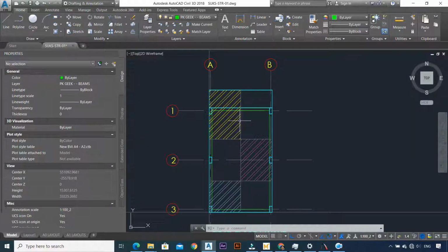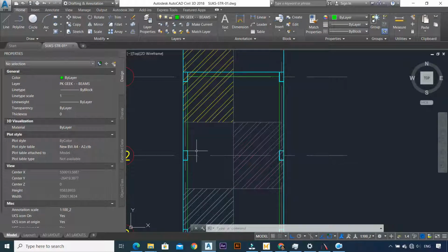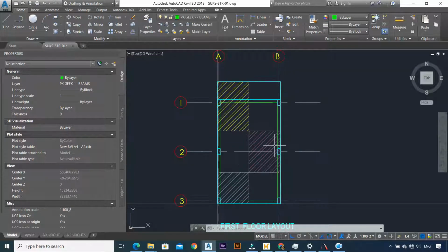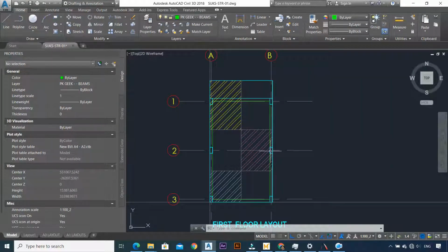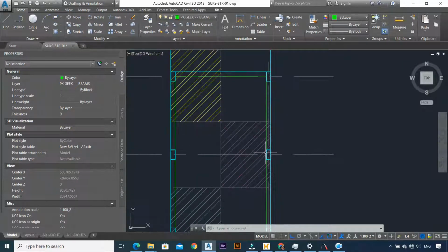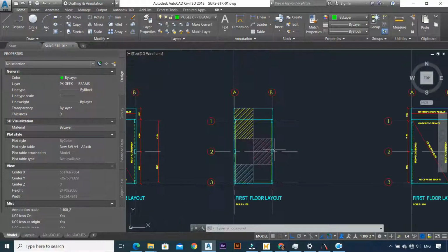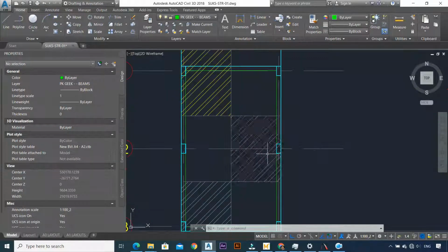By rule of thumb, we're just going to say the corner columns will obviously have one area. The external columns, which are not specifically in the middle, will have two, as you have seen. But if it's a middle column, that is to say it is surrounded by continuity on all ends, because this part of the column is continuous, but then the other side is discontinuous. There's no portion of the slab. That is why it's only given by two areas. So that is what you need to keep in mind.